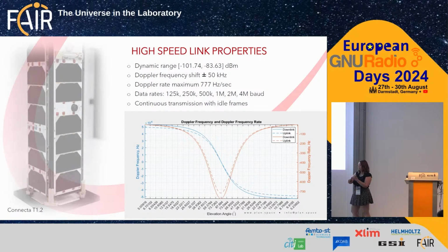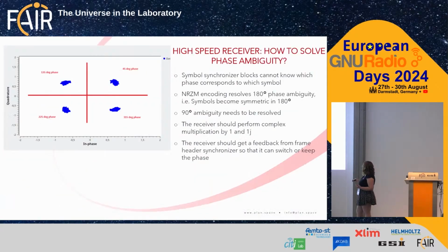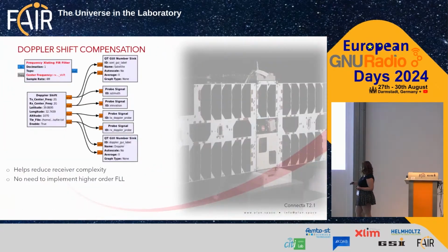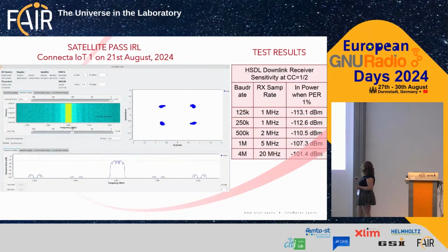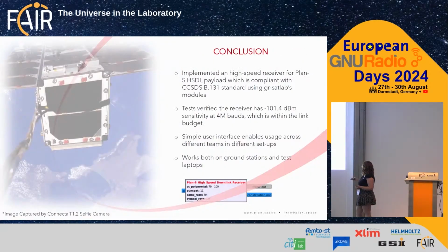So I have both a Doppler rate error and a shift error, and I've used GNU Radio to simulate that. I didn't include the outputs, but it was able to work with plus or minus 10 kilometers of TLE error, which is quite high.